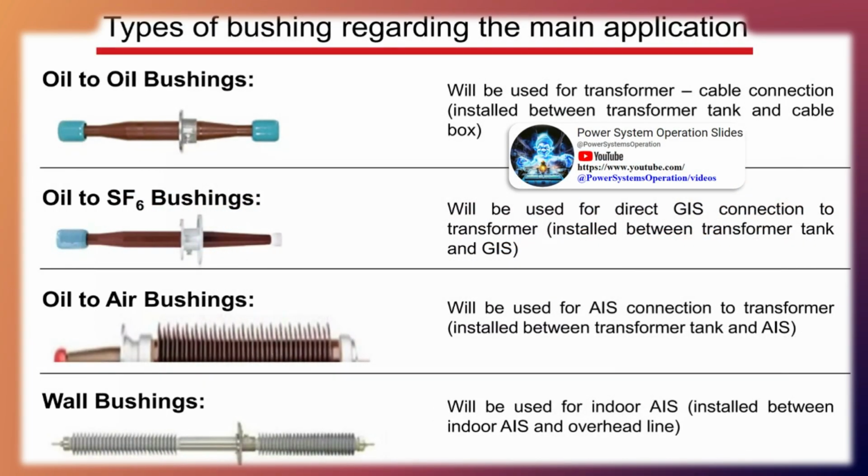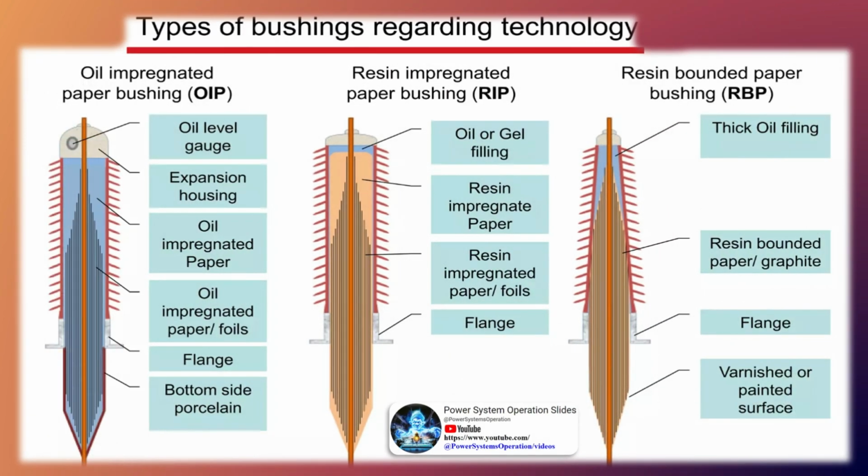Sensor design. IEEE standard C57.19.100, IEEE Guide for Application of Power Apparatus Bushings, offers the following guidance when selecting a bushing monitoring system/sensor. Bushing monitors are installed on bushing cap taps to allow for online testing and monitoring. These devices allow for continuous monitoring or periodic testing of bushings without removing the bushing from service. Since the monitors replace the existing cap tap cover, the user should ensure proper fit of the monitor to prevent moisture ingress into the cap tap.